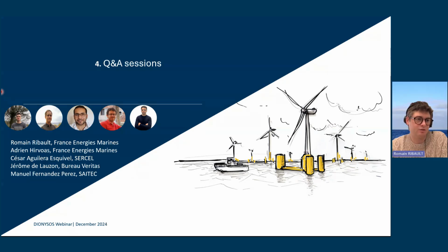And she asks about mooring line stiffness. Could differences in mooring line stiffnesses, measured versus theoretical, influence the dynamic, rigid body, tower eigen mode of the floating offshore wind turbine? Are you able to verify this? Well, I will say that depends. About mooring line stiffness, if we look at the mooring system stiffness as a whole, yeah, for sure, it will influence the dynamic of the model, and it will influence the rigid body modes. That's how we did calibrate the Zephyros model.